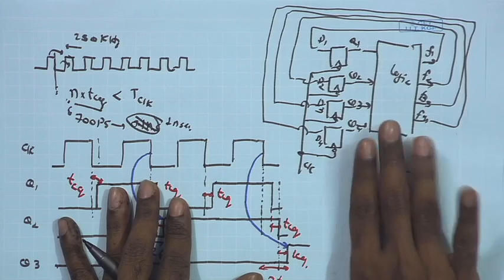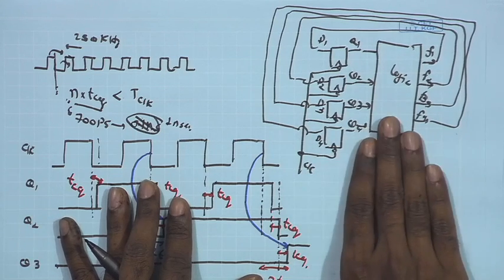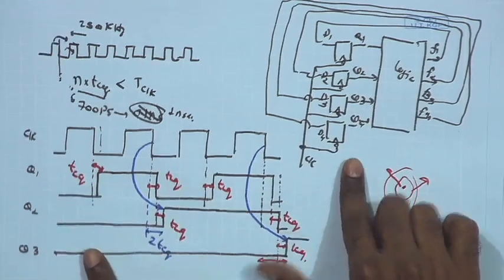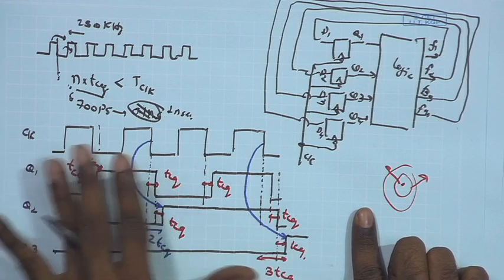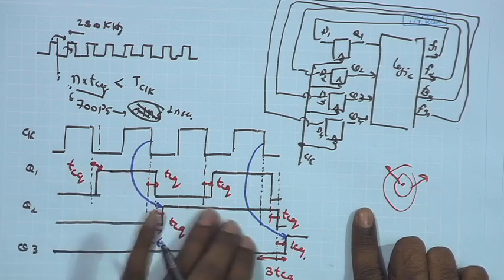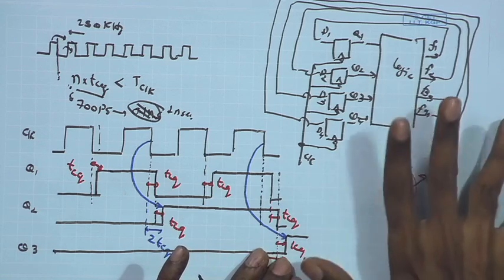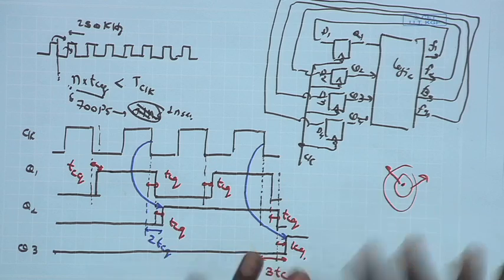But that can be implemented in ways where it goes relatively at a lesser rate as compared to the clock-to-Q delay. Clock-to-Q delay, we say that it is going to increase linearly as you go on increasing the number of bits in the counters. The clock-to-Q delay goes on adding linearly. Here it is not necessary, we can make sure that the logic is faster using some special scheme. So, these are the two schemes.